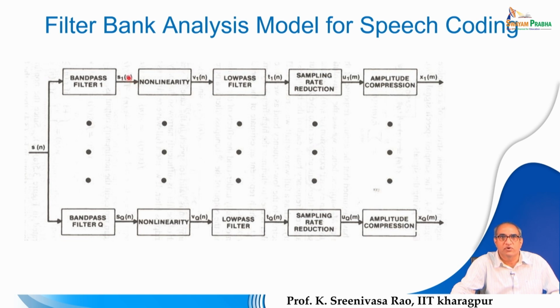So, therefore, all put together, the outcome of all these band pass filters, the 16 band pass filters, will split the speech signal into narrow band signals. Earlier the speech signal contained frequencies from 0 to 8 kilohertz or more, but here we assume that up to 8 kilohertz is reasonably good. So, by designing a set of 16 filters, each filter will offer a bandwidth of 500 hertz.